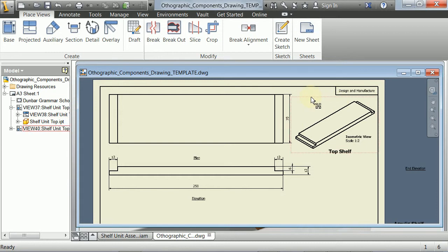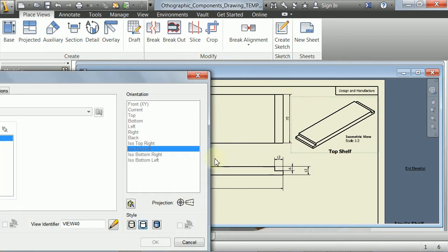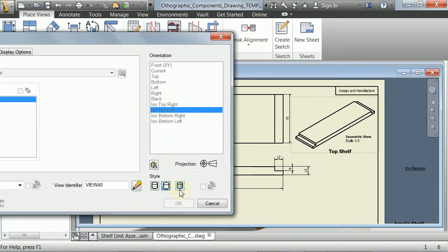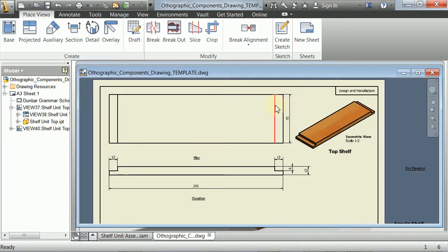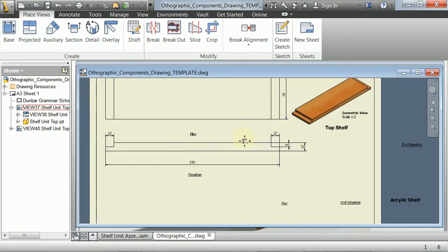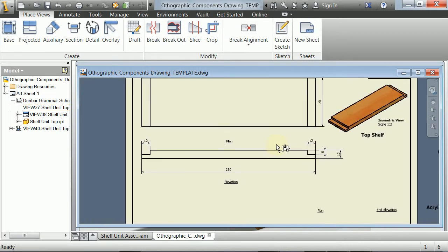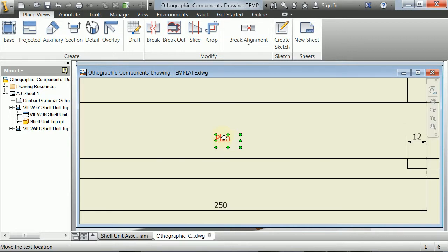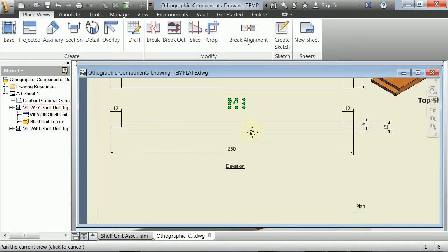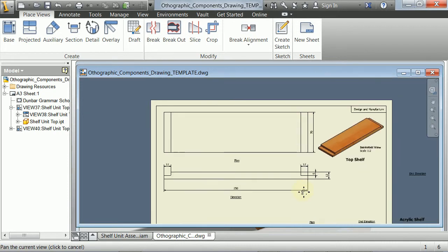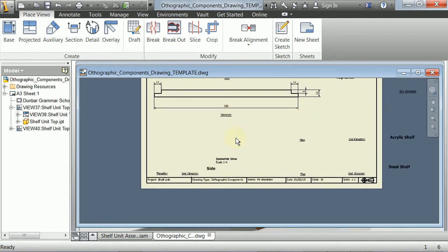So if I want to change this, for example, I can double click on that red box, click on this blue shaded view here, and that gives us a shaded view, which is a little bit easier to understand. So I've also got my viewpoint annotations in there. So I've got plan, which tells me that's a plan view, and I've got an elevation, so I'm happy with that. So that's that view complete.